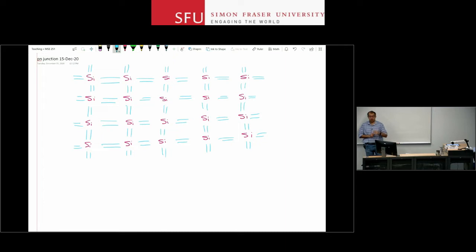Why do we like semiconductors? Well, that is the reason. We can change the resistivity very precisely and set it to where we want it to be, unlike for metals. For metals, if you have a piece of gold, for example, there's not much you can do in terms of processing to change the resistivity of that piece of gold. If you have a piece of glass, there's not much you can do to make it electrically conductive. But with the semiconductor, we have come up with some processing techniques to play with that resistivity quite a bit. And by that, I mean we have come up with ways to change the number of free electrons or charge carriers in a piece of semiconductor.